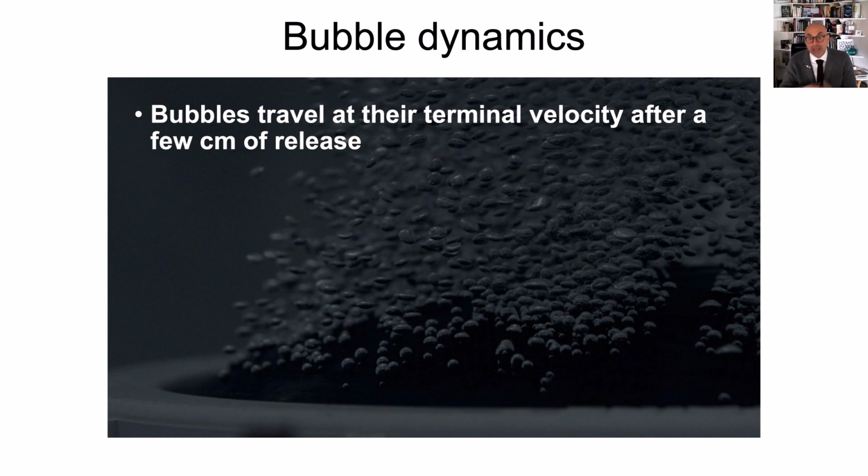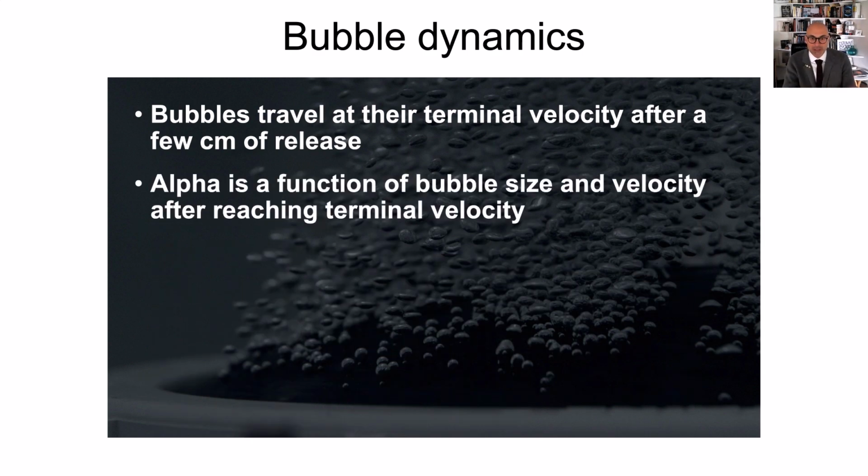So the jet area doesn't really transfer much oxygen because it's saturated, but the plume is what really transfers oxygen. So as soon as you exhaust their initial velocity, you slow down to their terminal velocity. If the bubbles are released with a pressure that is just enough to overcome the pressure drop and the hydrostatic head, what happens is the bubbles form and detach, and they start accelerating until they reach the terminal velocity. But the terminal velocity stands. The bubble expands going up, so the terminal velocity goes up going up, obviously.